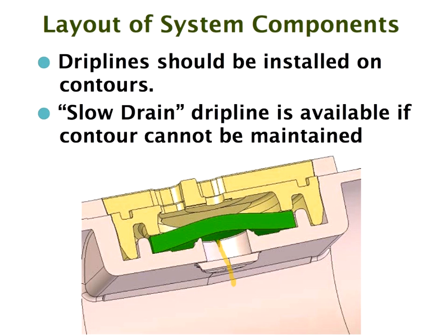And when the system switches off, this rubber diaphragm goes down, slows down the drain, and this slit allows the drain to take place very, very slowly. So the water will come out of the dripper and will follow a path like this, and then round there, and very, very slowly go back into the pipe.